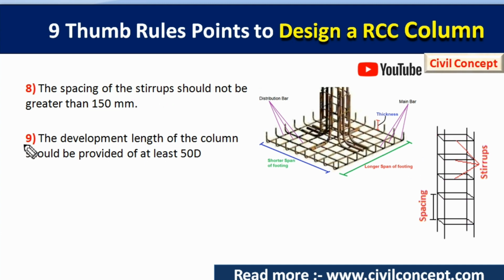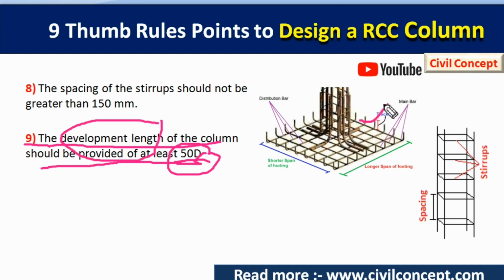Now our point number 9 and last point is the development length of the column should be at least 50 d. So what is 50 d? d is the diameter of the rebar. First of all, I want to tell you what development length is. You can see in this figure that the rebar has come like this and turned like this at the footing. This length is known as the development length. We have to provide this development length for a stable structure, and it should not be less than 50 d.